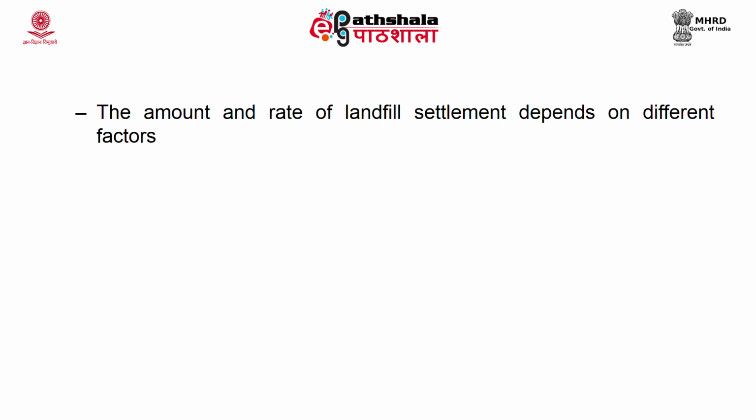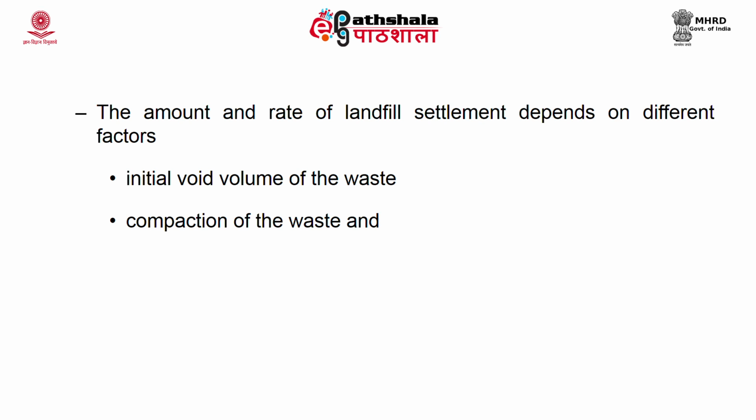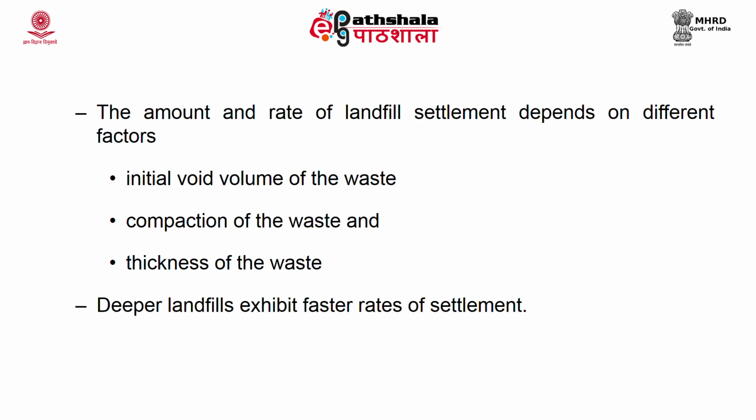The amount and rate of landfill settlement will depend on different factors. One is your initial void volume of the waste. It will also depend upon the compaction of the waste and the thickness of the waste. Normally, they say in deeper landfills you can find a faster rate of settlement.